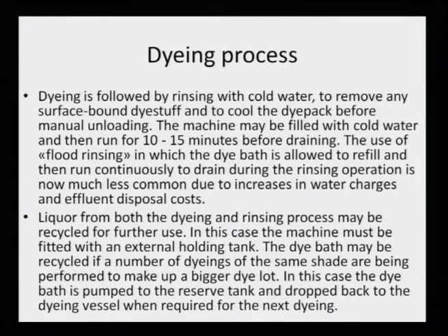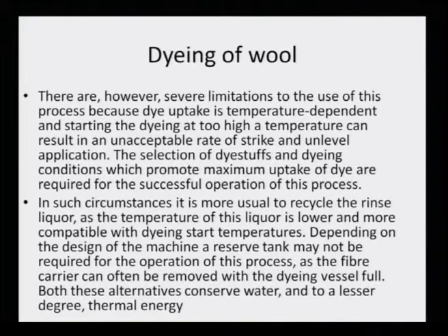Liquor from both the dyeing and rinsing process may be recycled for further use. In this case, the machine must be fitted with an external holding tank. The dye bath may be recycled if a number of dyeings of the same shade are being performed to make a bigger dye lot. In this case, the dye bath is pumped into a reserve tank and it can be reused. So, you see that it is such a facile process, and however severe the limitations may be, you have seen that wool dyeing is relatively very simple, and to be able to do this dyeing, the basic criteria must be kept in mind.